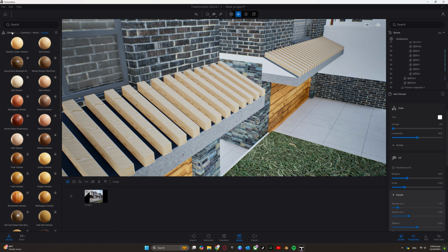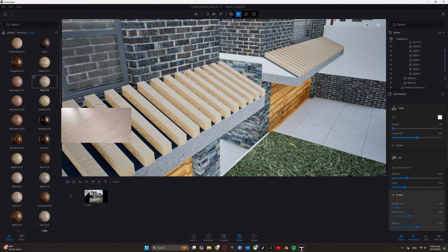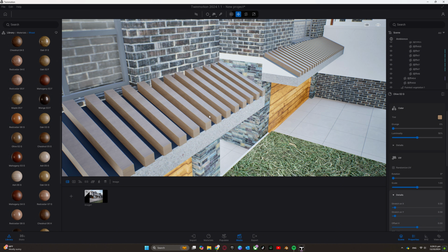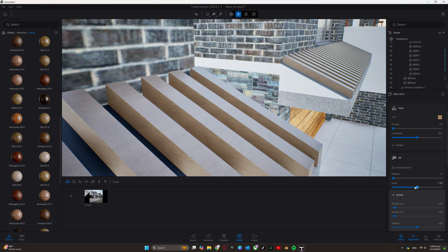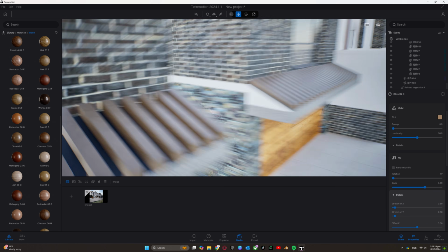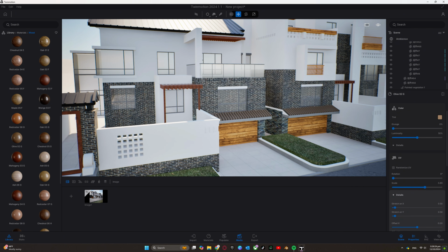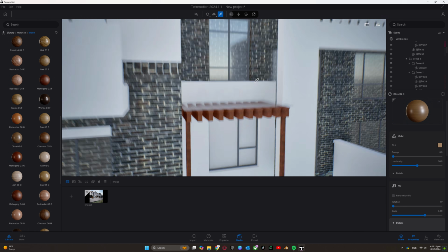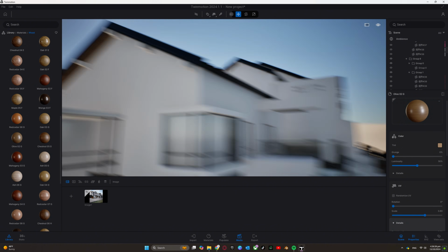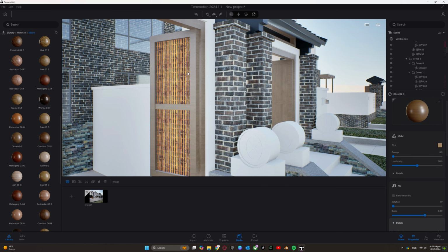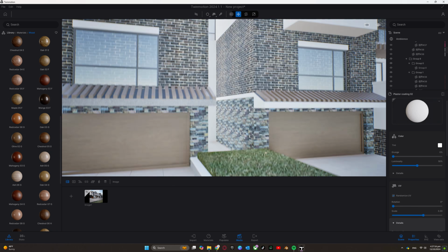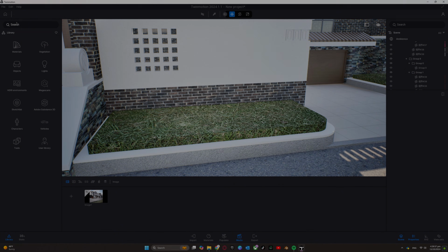Once that has been completed, we're going to go through and apply a timber texture to these slats on the outside. So I'm just going to use the Twinmotion material, and I'm going to use the Olive 02G. And I'm just going to increase the scale of that one. It's kind of a generic timber material that doesn't have too much grain in it, so it works quite well. So I'm just applying that to all the locations where the timber needs to be applied. In your case it might be different, as everyone's design and process is different.